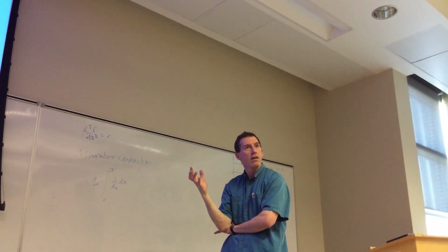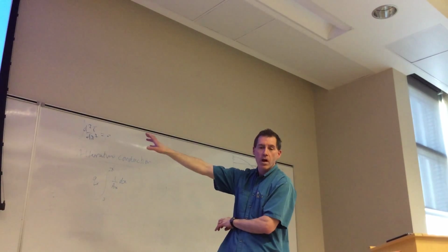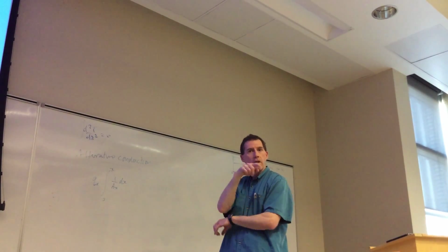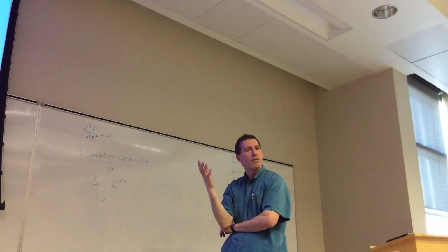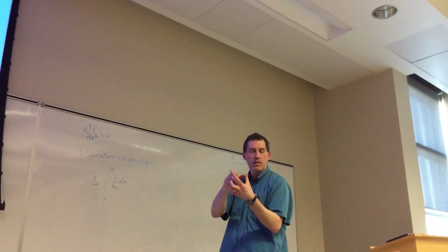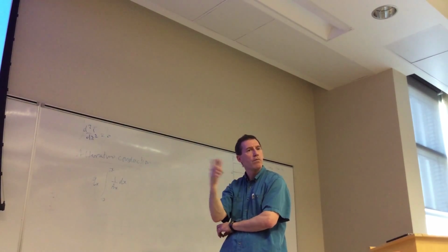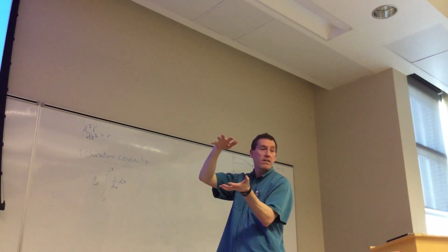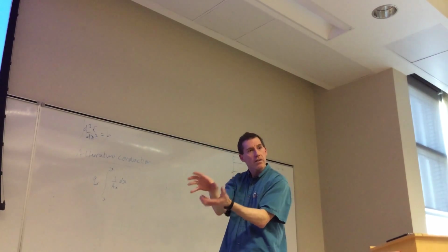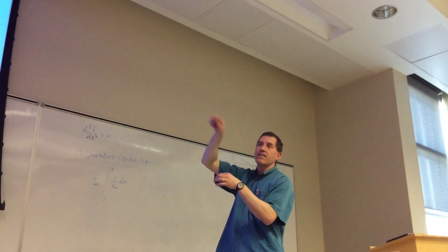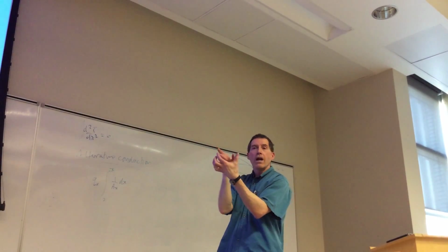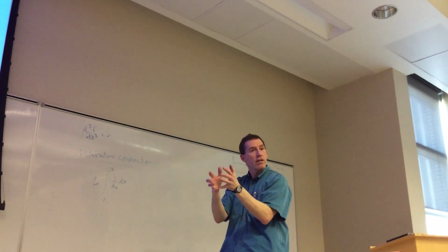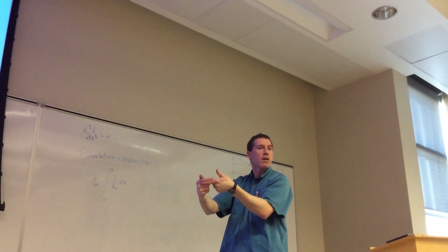Now, without saying too much, take the chapter 8 one where I did the internal flow, problem 8.51. It has helium in a tube from a reactor or something. Anyway, I managed to get a Newton-Raphson equation from that. And in that instance, all it was was writing 3 equations: the TS equation, the tube Reynolds number equation, and maybe a Nusselt equation. It's the 3 equations that go together, and they're all nonlinear, and it was just knitting those equations together correctly to get an F of T equation.